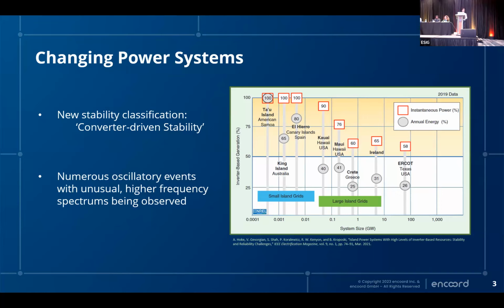And there's actually an entirely new classification for stability known as converter-driven stability. We're all familiar with rotor angle stability and voltage stability and frequency stability, sort of like the triad of classifications. Well, now there's converter-driven and resonance stability. Converter really encompasses all of these challenges that are associated with the interaction of these inverters amongst themselves.